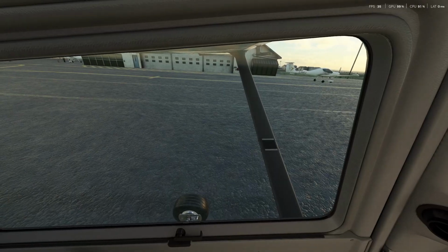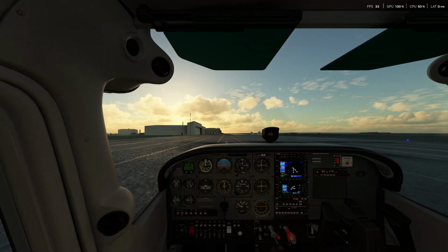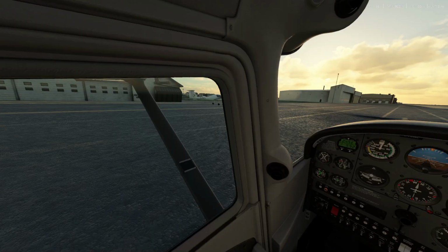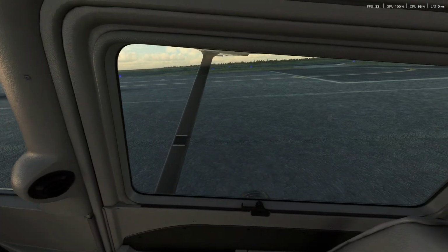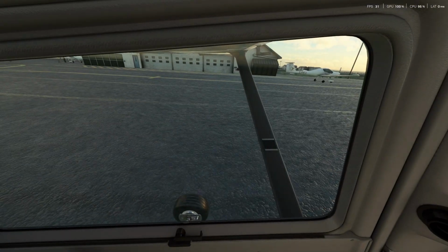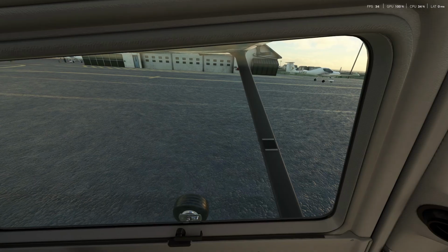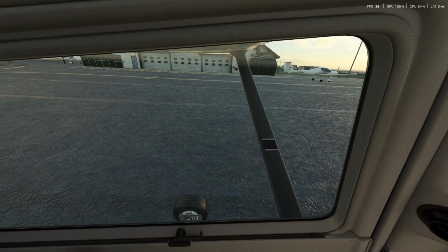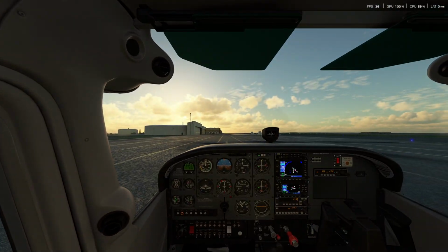Right, so for the taxi area we'll confirm clear, so we'll look left and right. We'll do a brake check once we start rolling. The steering, same thing, we'll do a steering check, and we'll check flight instruments. Right, so left is clear, right is clear, parking brake is off. Just give it a little bit of throttle here until we start moving, then we'll do a brake check. Right, the brakes are tested and checked.